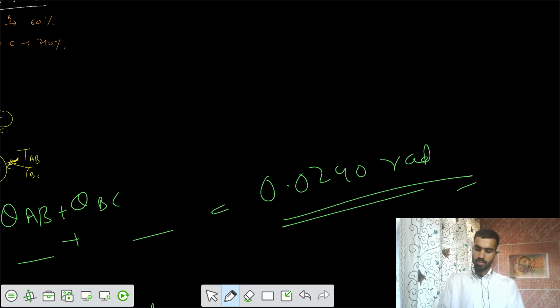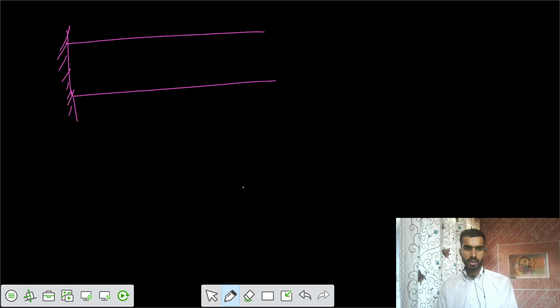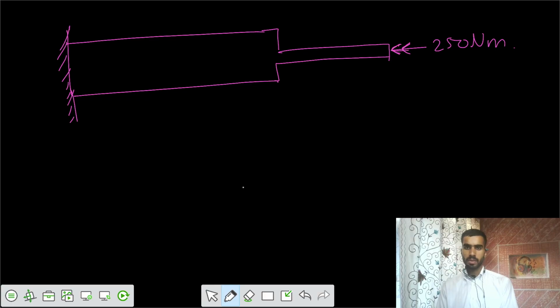And let's take the third problem of this kind. So we have one more that's saying there is a spout and there's some shaft attached here. After that there's one more shaft of decreasing diameter. You apply the torque of 250 Newton meter here. The two arrows represent the direction of thumb, which means a clockwise torque of 250 has been developed at this point.